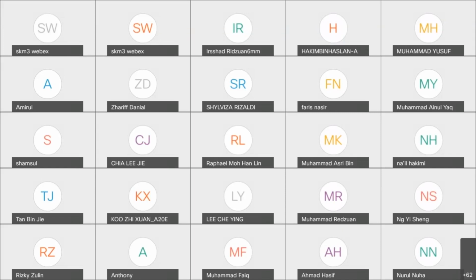the force required. So, based on the formula, shear F over A, we change it to F equal to shear multiply with A. We already have A and we don't have shear. To get shear, we use the formula viscosity times velocity divided with y.